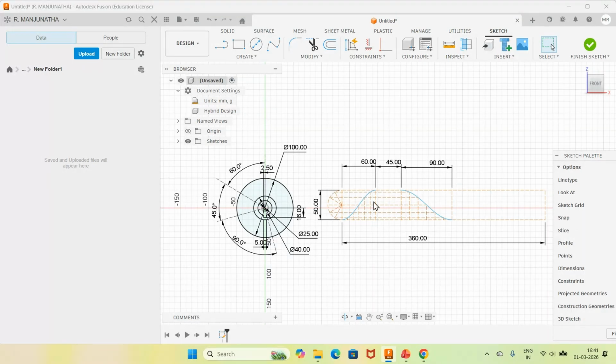You have 6 segments, so here also I need to have 6 segments. Then from there, 45 degree, that is once you have the lift of 50, then from there, 45 degree to the same distance or the same displacement. Again, the outward stroke, that is from 100, again it comes back. So during this period, from 100 to this 50, you will be having this descent. And then the remaining period will be 360.